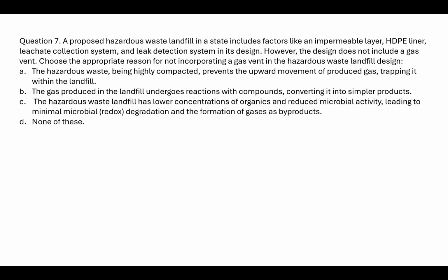So I got one answer as C. So C is the correct answer. The hazardous waste has a much lesser organic concentration. So organic carbon will not be present for the microbes to degrade the waste. That's why very little microbial degradation is seen, and the formation of gases as byproduct is very less. On the other hand, municipal landfill has a very high amount of organics because of the food waste and also other types of waste like tree cuttings and all.